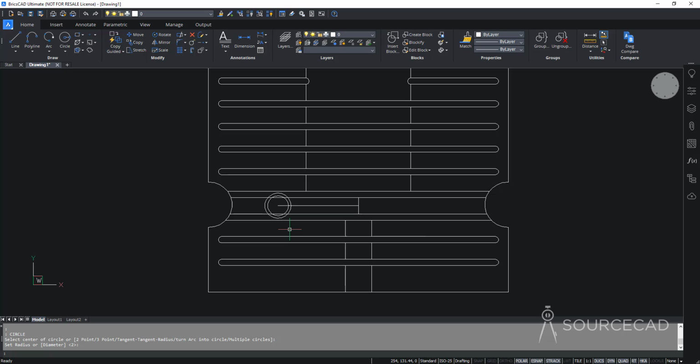Now we'll make the rectangle. So I'll go to rectangle, and we can now make the rectangle maybe somewhere here. So now this length is 8 and tab key, height is 6, enter. There is the rectangle. Now I'll just move it right here. So I'll select this, move tool, and I'll move it with respect to the midpoint, this geometric center. So I'll just track it. Here is the geometric center, and I'll move it right here. Okay, now we can get rid of all these construction lines yet again.